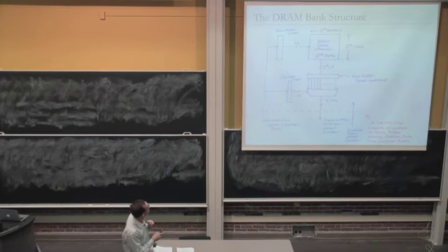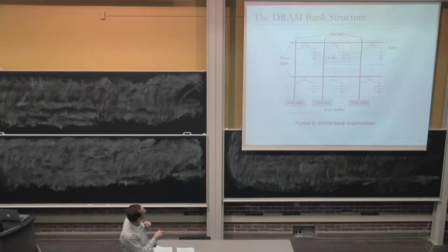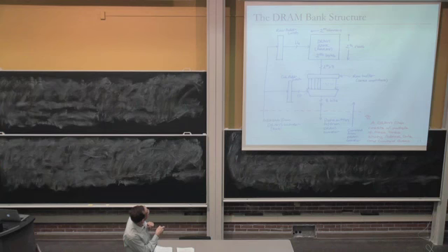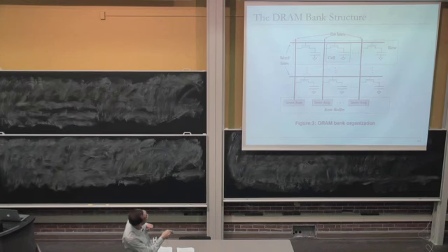You should be comfortable with this. And we'll cover this in a little bit more detail. Basically, if you look at it at a little bit lower level, these are the DRAM cells. And each cell is connected to a bit line and a word line, if you will. This word line is activated when you activate the row of cells. And this is the row of cells here. And you can have a column of cells that contain multiple of these together. So each cell is also connected to a sense amplifier, which basically amplifies the charge stored here to detect whether a 0 or 1 is stored.